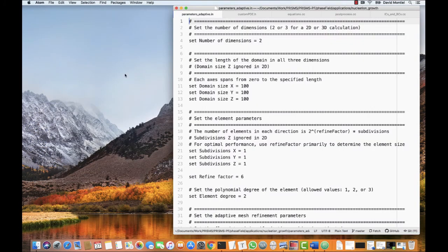This is a parsed text file where we can specify most of our simulation settings, such as the model constants, simulation parameters, the mesh settings, and simple boundary conditions. Every time we run the code, this file is read by the executable. So if we have compiled the code and need to change the settings in the file, we can just edit, save the changes, and rerun the code without having to compile.